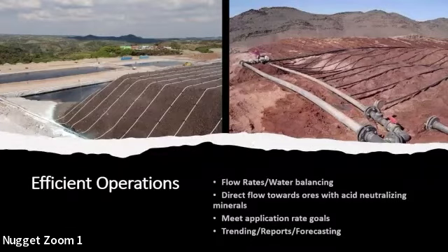So in this case, all samples were much below 80%. So the concerns related to static liquefaction, even if not totally eliminated, are still very low. The result summarizes that the maximum saturation found was 86%. One of the samples just overpassed 80%.